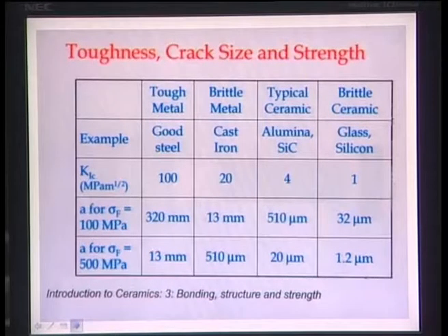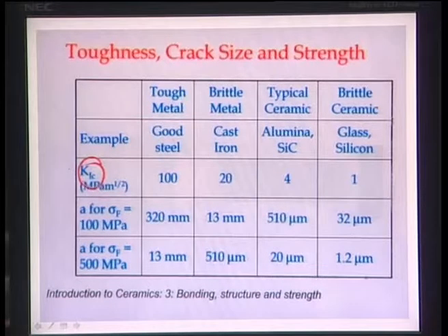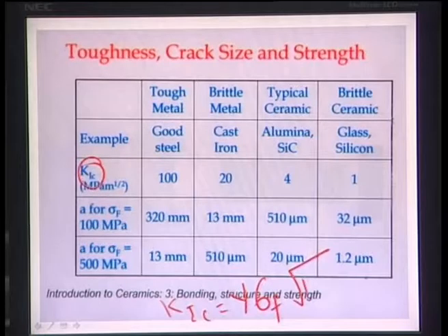Now, this essentially tells you that strength and elastic modulus largely depend on the pore size. Similarly, K1C, I repeat, K1C stands for critical stress intensity factor under mode 1 loading. In the last lecture I mentioned that K1C you can define as Y sigma F root over pi A. What are the different terms here?